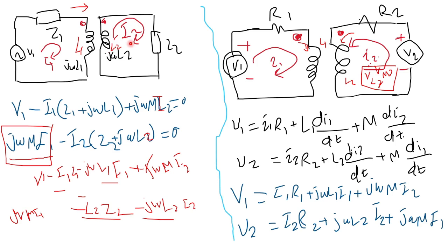The rule is that the currents I1 and I2 should both enter the coils at the dot, or both leave the coils at the dot. Here we have I1 entering the coil at the dot, while I2 leaves the coil at the dot. So this is an opposing connection case, meaning the mutual inductance voltages would have a reversed polarity compared to the self-induced.